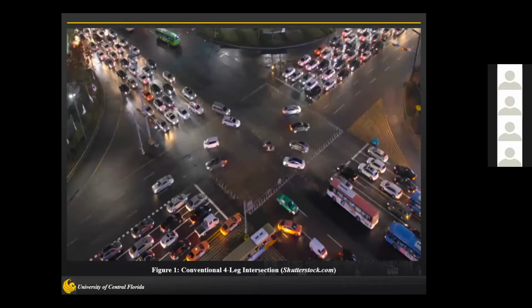Several intersection designs have been proposed as alternatives to the four-leg conventional intersection design in order to improve traffic safety and operation at intersections. The effectiveness of alternative intersection designs comes from the reconfiguration of some movement patterns, mainly the left turn movement, and prevention of conducting some movements directly at the main intersection by allowing them to be performed upstream or downstream of the main intersection. This reduces the number of traffic conflict points between movements, which results in two main advantages.